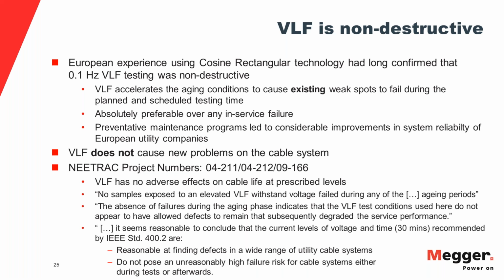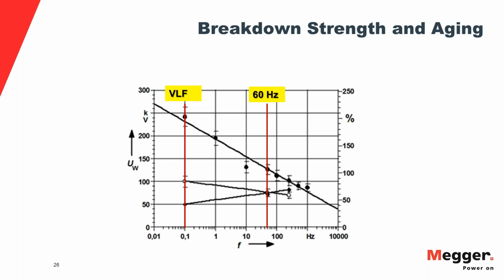Again, the destructive test would be the step test, and there are also procedures and standards for the step test. There's an IEEE procedure and an IEC procedure, which is a bit different. So then another thing is the VLF test. When people hear the test value of 3 times operating voltage, some people think they are overstressing the insulation.